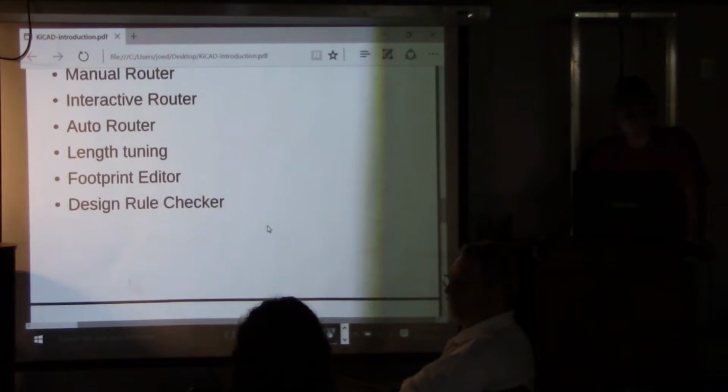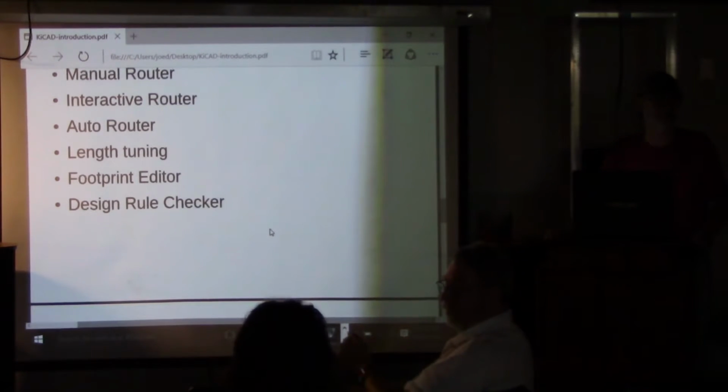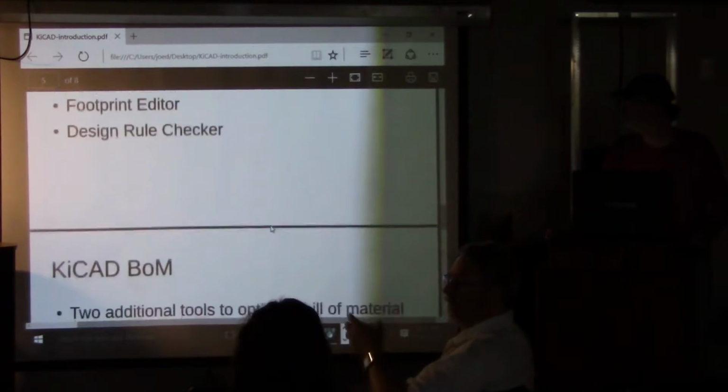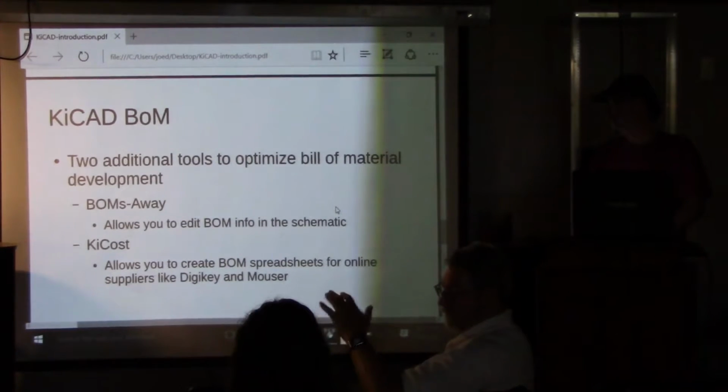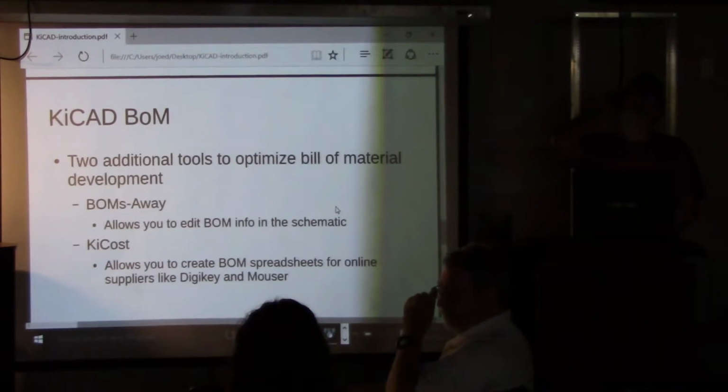It is hard to find every component you'll ever use, so you'll usually end up making some parts. For myself, I've been using it multiple years, and I generally either take a part out of the library and make sure that it fits my application, meaning that the parts that I picked for the bill of material, I verify every spec, and I put it in a separate library just for that part, or just for that board. So I've always found the limiting factor in the CAD program, the PCBs, is the footprint.